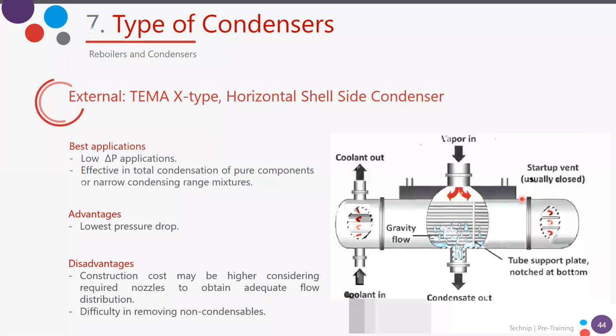For example, if we have just 2 nozzles without the distribution, we will have one nozzle here, another nozzle here, and we need to place also a vent nozzle. This vent nozzle will be placed in the middle.